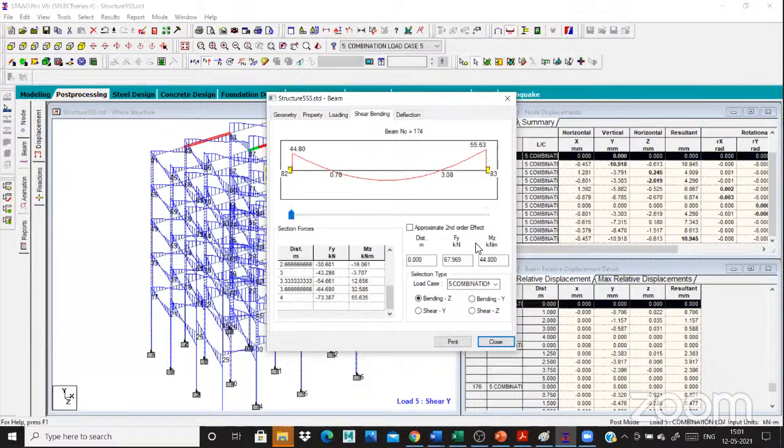You click this, automatically it will change these values. This is 56. I need the center value. Automatically click this center value. This is the dimension. I need the center value. Click this, automatically it's the center value. Or otherwise, this might be 1.5. Click this, it is 1.5. I need this 3-meter beam, or 2 meters. 2 meters, this is the center. Click this, automatically the shear value is 2 meters and base 1. This is the method to see the single beam in Staad Pro.